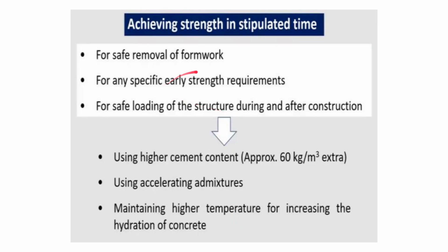So, achieving strength in stipulated time. Why is it required? It is required for the safe removal of formwork, for any specific early strength requirements, and for safe loading of the structure during and after construction.